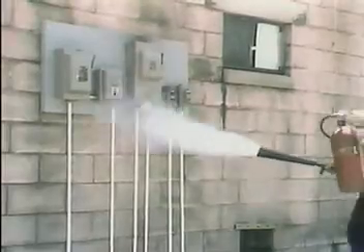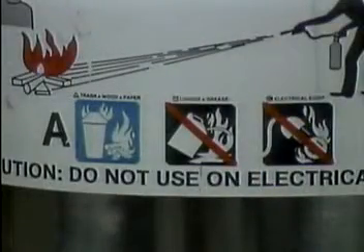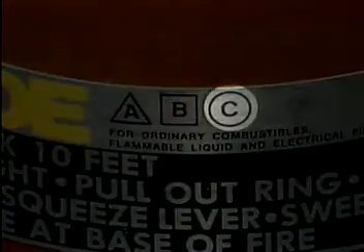If you're going to put the fire out, be sure to use the right type of fire extinguisher. Fire extinguishers are classified by the type of fire they're designed to extinguish. A Class C fire extinguisher is used for electrical fires. Class C extinguishers often contain carbon dioxide, CO2, which is ideal for electrical fires because CO2 puts out the fire without conducting electricity. You should never use water to put out an electrical fire. Water conducts electricity, and it can cause an explosion or create hazardous paths for current flow.